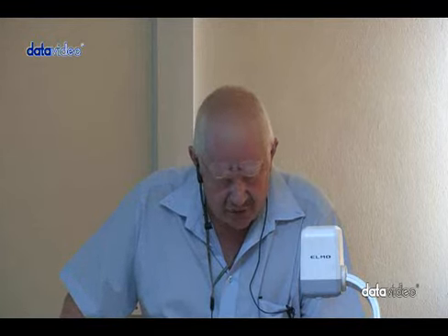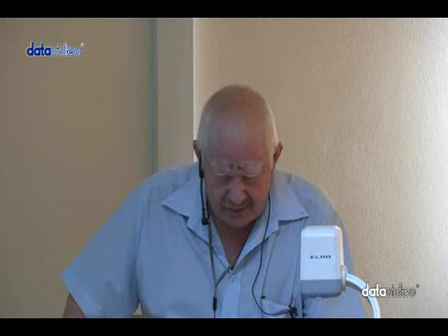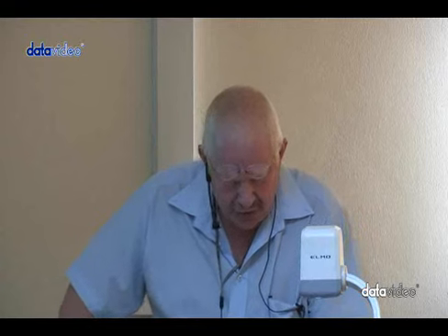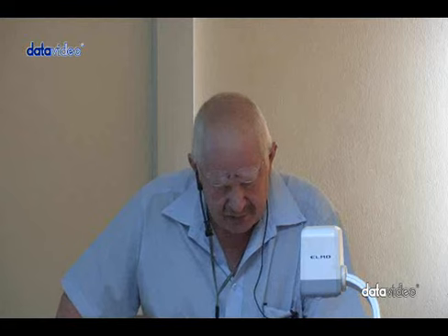As you have learned, a BJT can be represented in an AC model circuit. Three amplifier configurations are the common emitter, the common base, and the common collector. The common emitter configuration has the emitter as the common terminal, which I will show you just now, or ground to an AC signal. Common emitter amplifiers exhibit high voltage gain and high current gain, some characteristics of a common emitter amplifier. And of course the common collector and common base configurations we will cover in sections still to come.